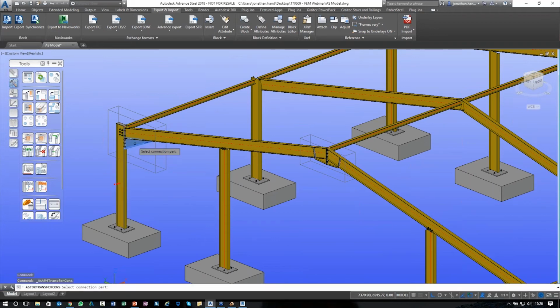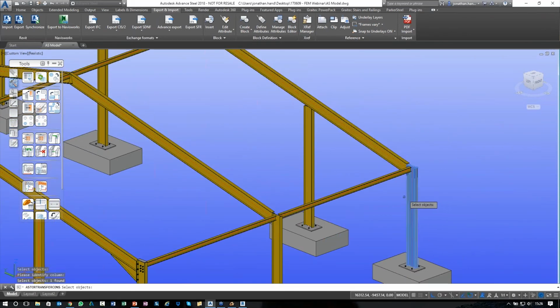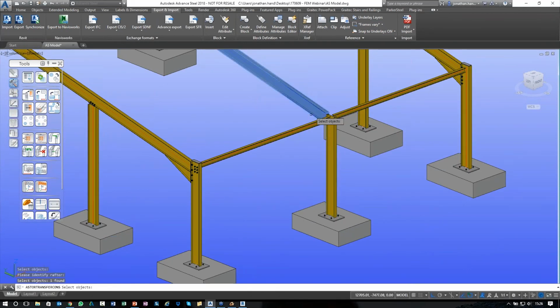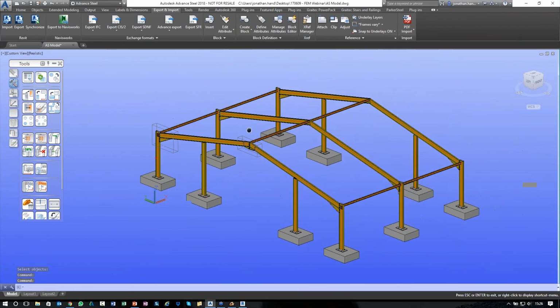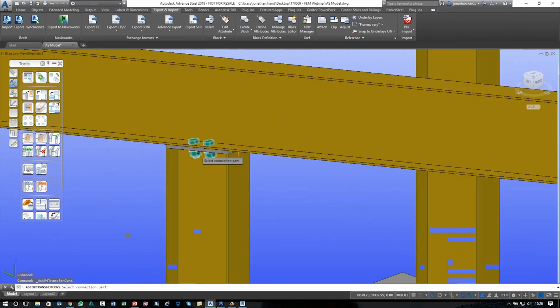So you can see that we're now starting to connect the Revit out to an FEM analysis. We can also upload it to the cloud, and we can also start to affect changes, and it can definitely speed up the advanced steel design process because we don't need to redraw anything. Everything is set out from my Revit file. I'm just going to quickly save that. For advanced steel, what we do find is if you're sending it back to Revit with the reflected changes, I do find that sometimes we work better and map the sections better if everything is pre-numbered.